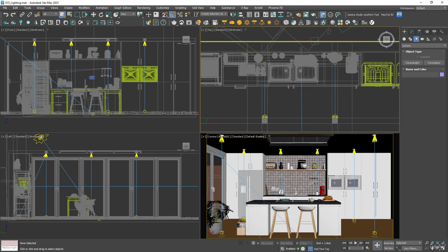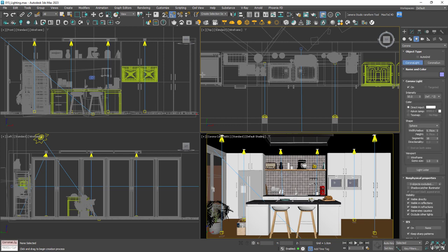Let's add some more lights to our scene. So I want a light that goes along this shelf, and we modeled the shelf so we could put a light behind there earlier. We're also going to add some bulbs to our spotlights and some lights to our oven. So we'll go to the Corona toolbar, create light, and I'll create that in the top view just about where the shelf is. And we actually want this to be a rectangle.